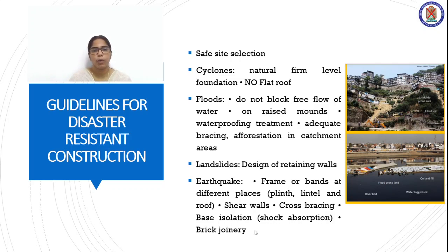and vector-borne diseases. For earthquake resistant construction, it is better to avoid hillside slopes and areas having sensitive and clayey soil. It is preferable to have several blocks on terraces rather than one large block with footing at different levels.